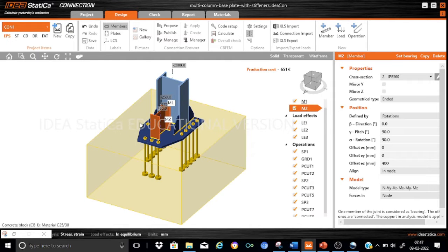So in tutorial 16 and 17, we discussed rectangular and circular base plates for single supported sections. What makes this tutorial unique is that it supports multiple columns as shown here. The base plate has a polygonal shape. And the third one is that the base plate, anchor bolts and pedestal are modeled not using the standard procedure but through a different approach. Now let me quickly take you through the different operations performed to complete this model.